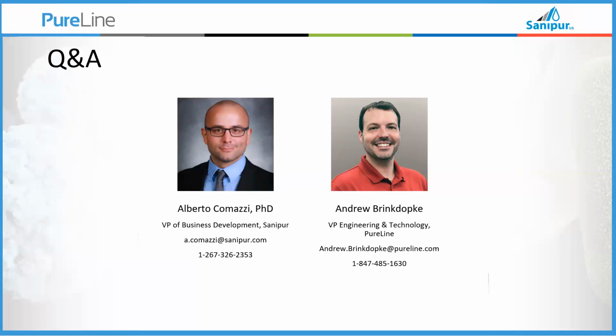Thank you. Likewise for the equipment shown here, it doesn't speak to all chlorine dioxide systems, but the one shown here runs on Allen Bradley based systems. So you can take discrete inputs and outputs for run statuses, or connect over Ethernet IP through a Cat5 cable to monitor all the parameters in the systems. Systems are also available with cellular remote connection, which allows for text and email communication of reports and alarms.